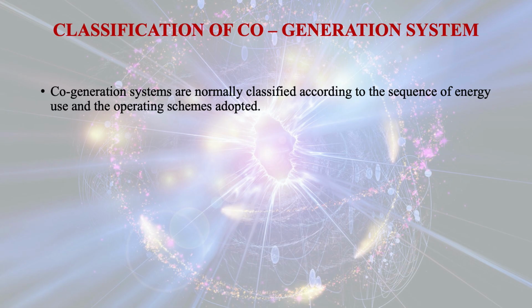The remaining 1 minus m1 kg of steam is further expanding in the turbine, but at stage 3, another m2 kg of steam leaves the turbine and enters into the heater 2, and the remaining 1 minus m1 minus m2 kg of steam will further expand in the turbine from state 3 to state 4, and here point 4 is the entry point of the low pressure, low temperature steam finally coming out from the turbine and entering into the condenser.